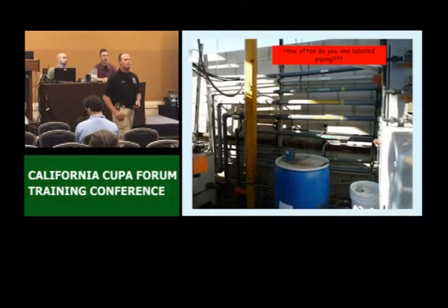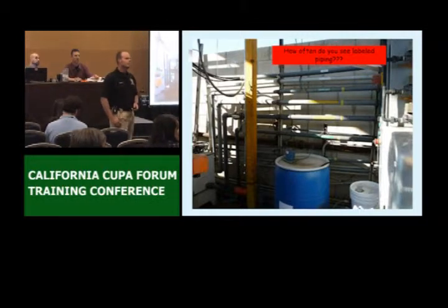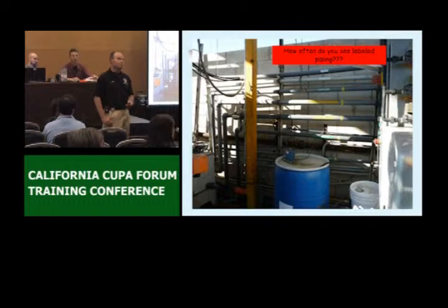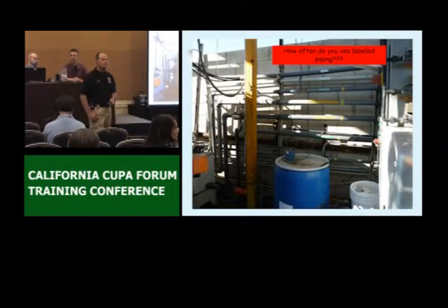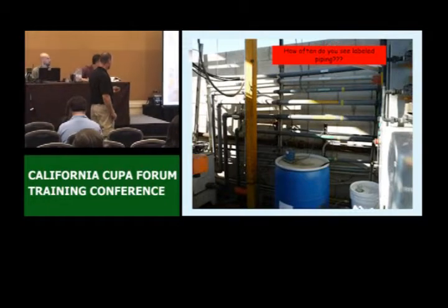One more thing as far as secondary containment: if you're going to be inside, fire code also requires the 20-minute sprinkler flow. Oh, that's true. So then you're going to have additional protection, if it's inside, right. Same facility. This is kind of cool.